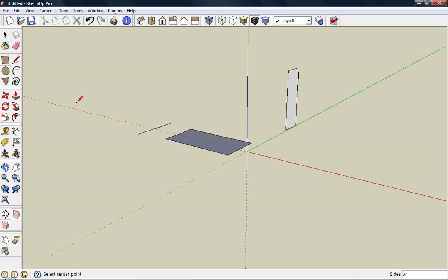Swing over here and grab our circle tool. Circle tool is pretty easy to use and understand. First we'll set our center point by clicking with the left mouse button and then pull out to the radius we're looking for. Once it's set, we can always go back and change the radius by entering a new number into the measurement toolbar. So say 9 inches, and the circle will automatically resize. Now, just like the line and rectangle tool, I can continue to enter new measurements into the measurement toolbar to resize this circle. That is, unless I've moved on to another operation.